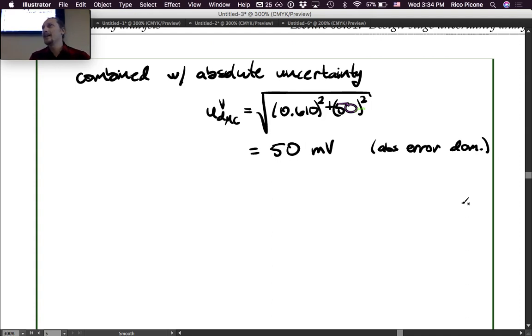They're okay for some voltage measurements, but high precision, they're not. They're more made for being inexpensive and able to do lots of things. All right, some high-end ones can do better, but it seems like you have very diminishing returns. You spend way more money and you get a little bit more resolution, a little bit more accuracy.